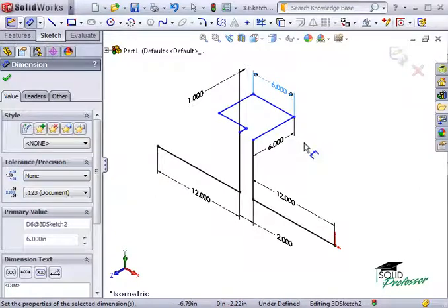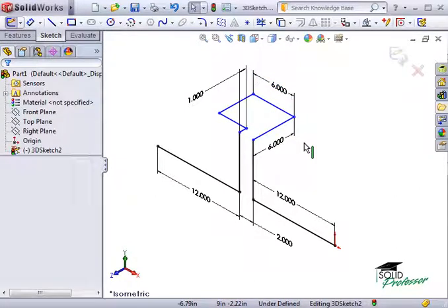As you progress with defining a 3D sketch, remember you can always stop and drag the remaining blue geometry to find out what remains underdefined. I recommend you do this more in 3D sketches than in 2D sketches. The reason is that in 3D sketches, it's possible to add many relations that are redundant or unnecessary. Rather than adding relation after relation, check to see what else you really need to define.